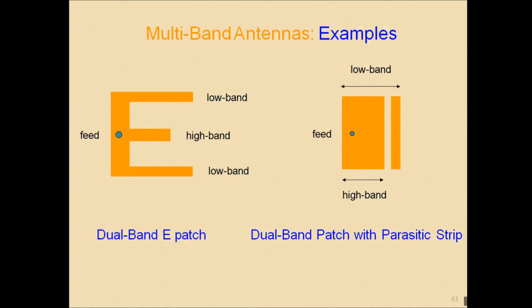So now the narrow bandwidth problem of the microstrip antenna can be eliminated with the help of different structures and shapes. But to cover very high frequency ranges, you have to go for an array of antennas, not the multi-band antenna. These structures address the problem of increasing the bandwidth with the help of a single antenna only. The single antenna will work for multiple bands of frequencies.